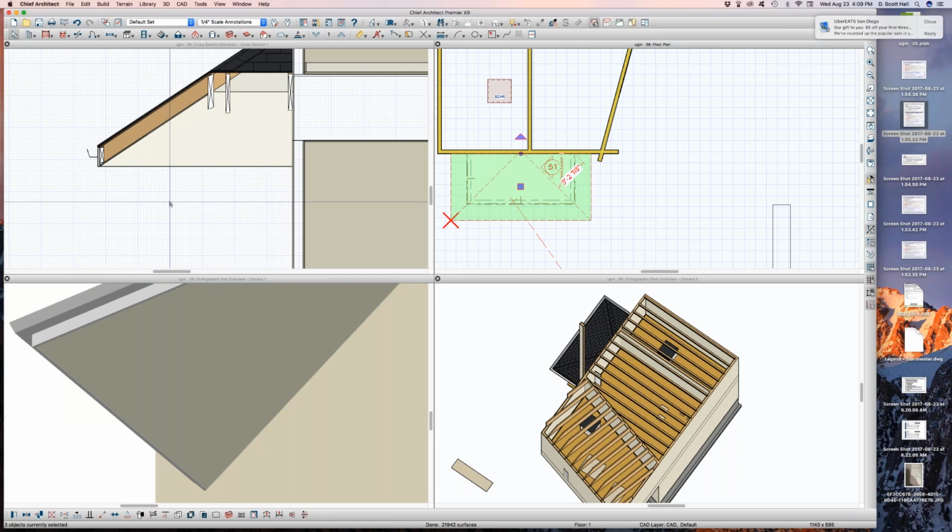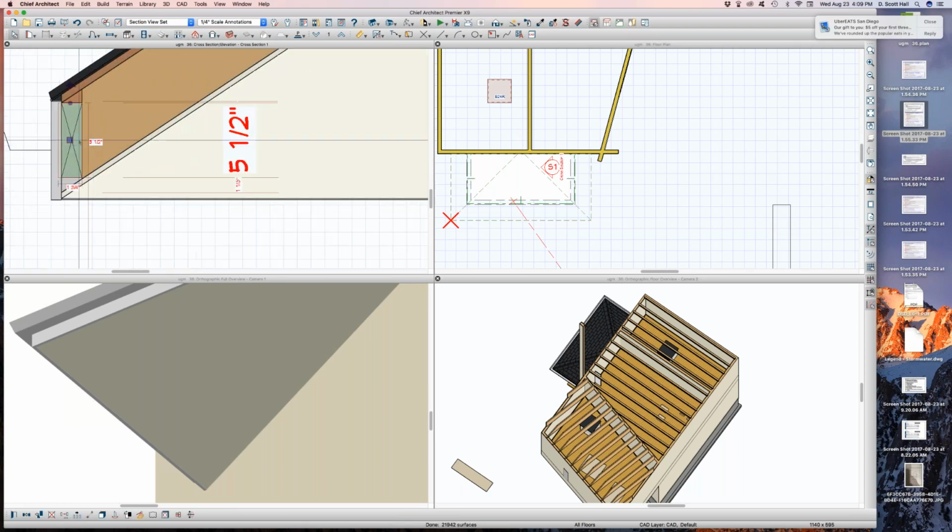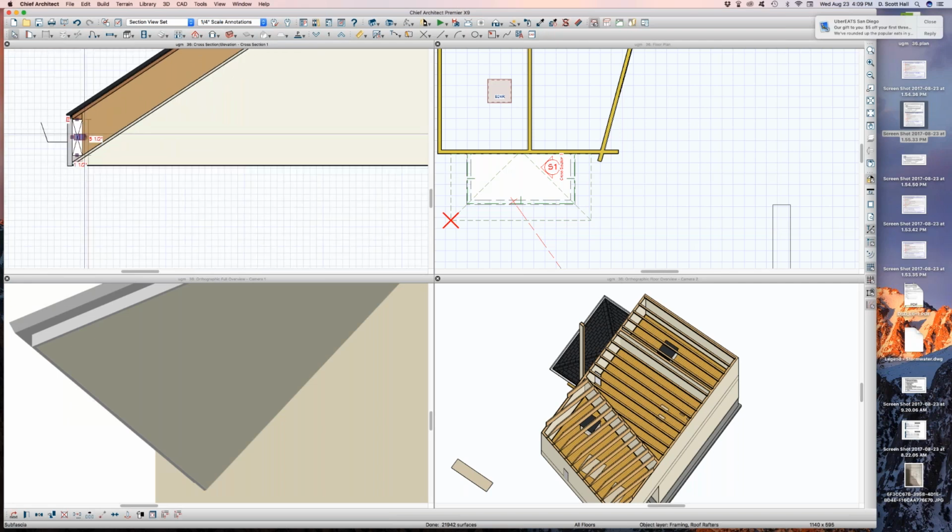What did you do differently? You can do it either way. You can have a box soffit and then the soffit material continues on up for a sloped interior ceiling, or you can slope it right from the fascia. Yeah, it forces the framing in the room to be the same size as the framing at the eaves. Yes, and whatever this is, the subfascia, that's what controls it. You get a continuous sloping ceiling from the eaves right up through the room.